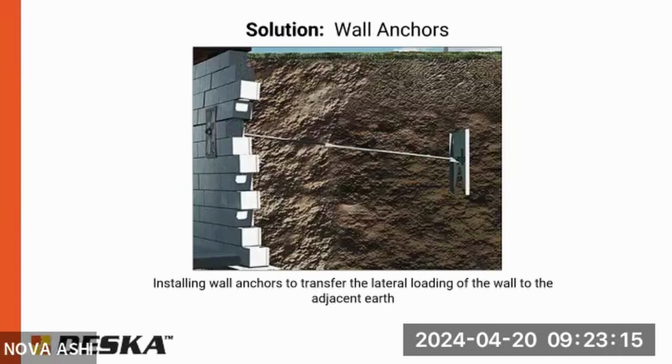And if you're going to do that, you have to leave that joint open. But we generally don't recommend this type of repair unless it's kind of a last resort. We prefer not to be bracing a lateral wall with soil that can move and expand and contract depending on a lot of external factors.